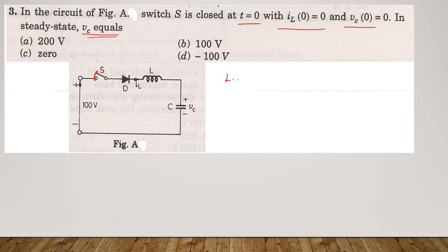And what is the equation? L into di by dt plus 1 by C into integral I dt, that is equal to Vs. Apply the Laplace transform.